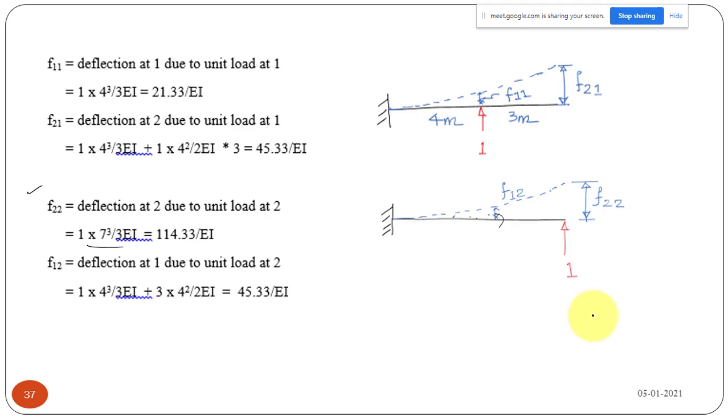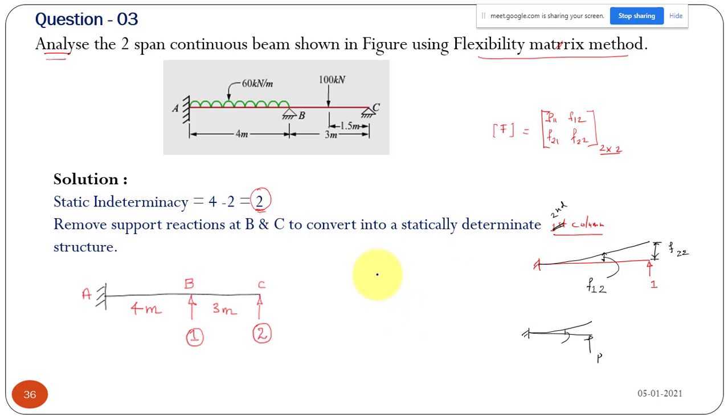You can get that. So maybe you have to do it like this only. Suppose I have a cantilever beam with a force P here, and let us say this point is some point A and B. My objective is, at the free end you can easily find the deflection, that is PL cubed by 3EI. That is simple.